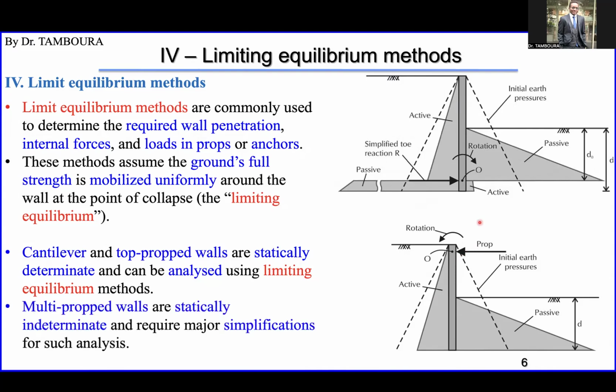Okay, so if you have a multi-propped wall, for example, with several supports, these walls are statically indeterminate and require major simplification to do this kind of analysis.